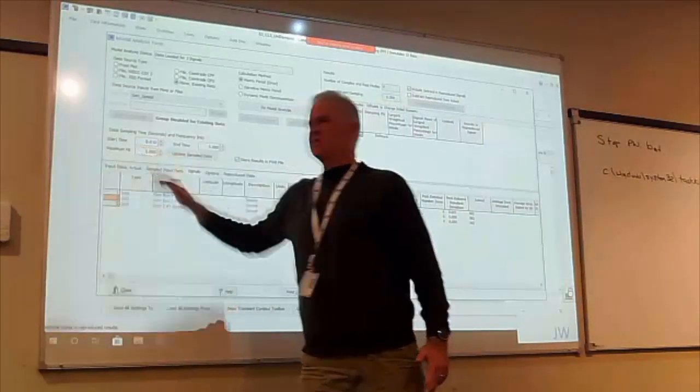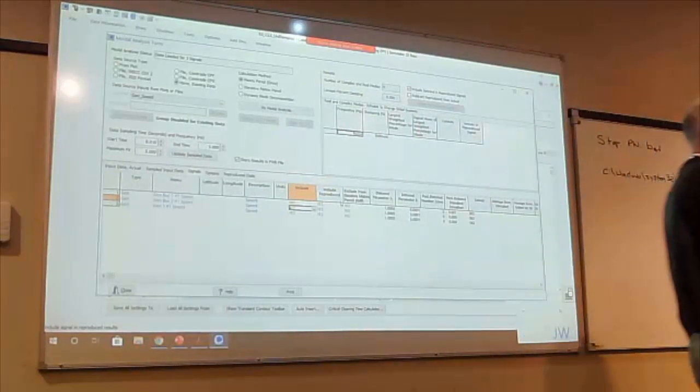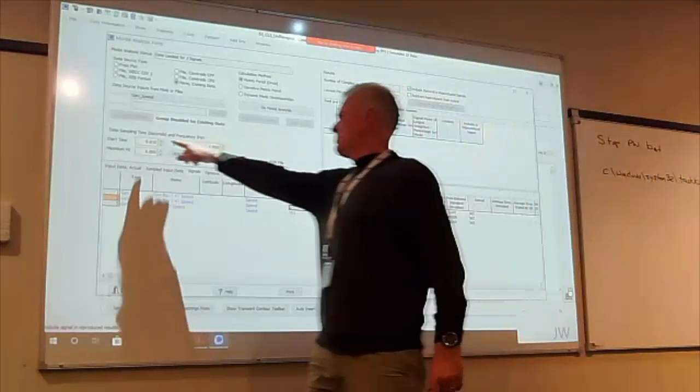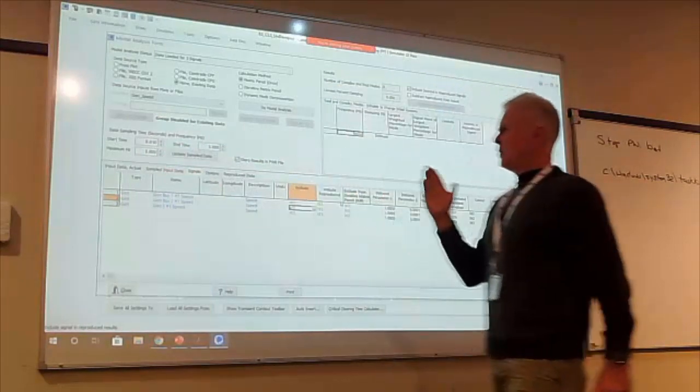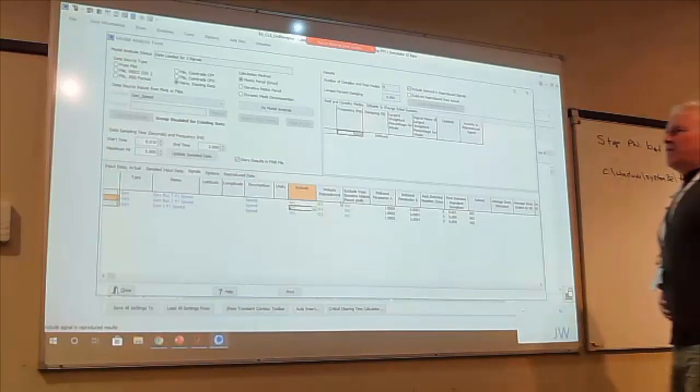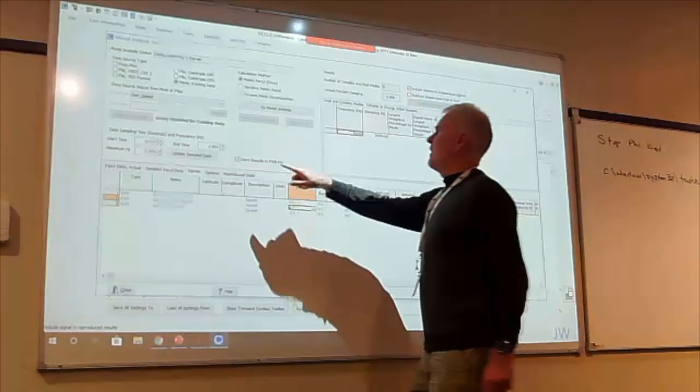And what is the maximum frequency that we're interested in? It's going to sample it at twice that maximum frequency. So here it starts not at time t equals 0, but by default it'll start after the last event. We put on this little fault, so we're going to start after the last event, just 100th of a second in. Just take the default of 5 hertz and an end time of 5.